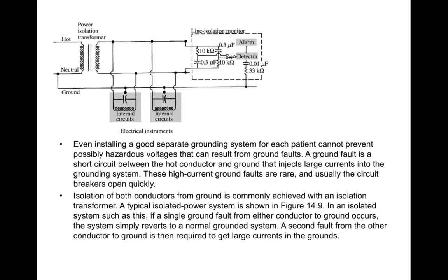And then sometimes there's even a double layer of safety where the power entering the room in general is isolated through an isolation transformer. So that is typically a way that is used to address ground faults. It can also address things like lightning or some other external force that enters the building and somehow increases the potential on the ground.